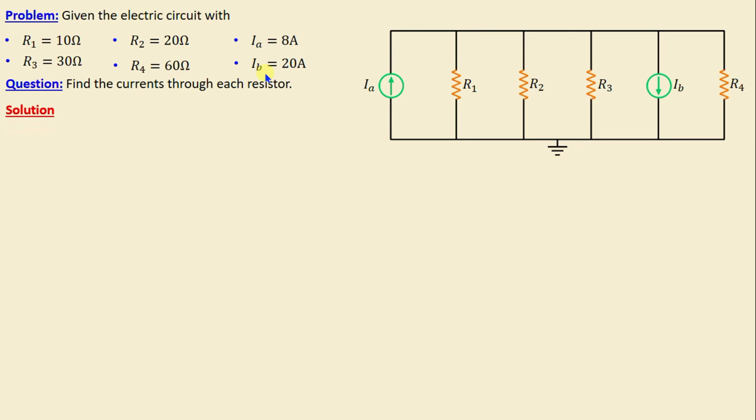In this network, all branches are connected in parallel, resulting in an equal voltage across each branch. Let's start first by labeling this node as node 1. And after, I will assign the voltage VO to this node. Next, we need to select a reference node in the network. The reference node is typically chosen as the node with the most connections or as the ground node.